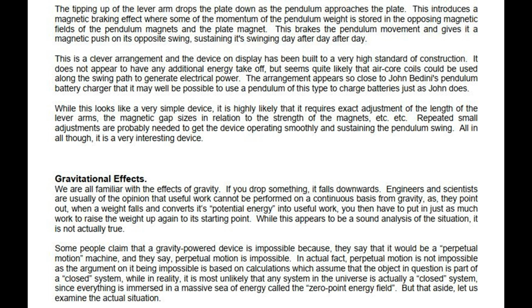While this looks like a very simple device, it is highly likely that it requires exact adjustment of the length of the lever arms, the magnetic gap sizes in relation to the strength of the magnets, etc. Repeated small adjustments are probably needed to get the device operating smoothly and sustaining the pendulum swing. All in all though, it is a very interesting device.